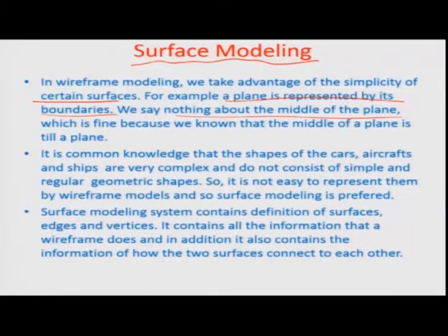Further to add complexity, we know that shapes of cars and aircraft are not that simple, and ships also are very complex, so they do not consist of simple geometries anymore. Representing the whole feature only with boundaries is not a very good idea, particularly when we talk about creating a data structure so that a three dimensional plane can be seen. Visualization generally has been enhanced because of CAD technology. So, why not utilize it fully is the next question, and so a complex data structure needs to be developed, so that you can plot in terms of a surface with control of each and every point on the surface that we are constructing.